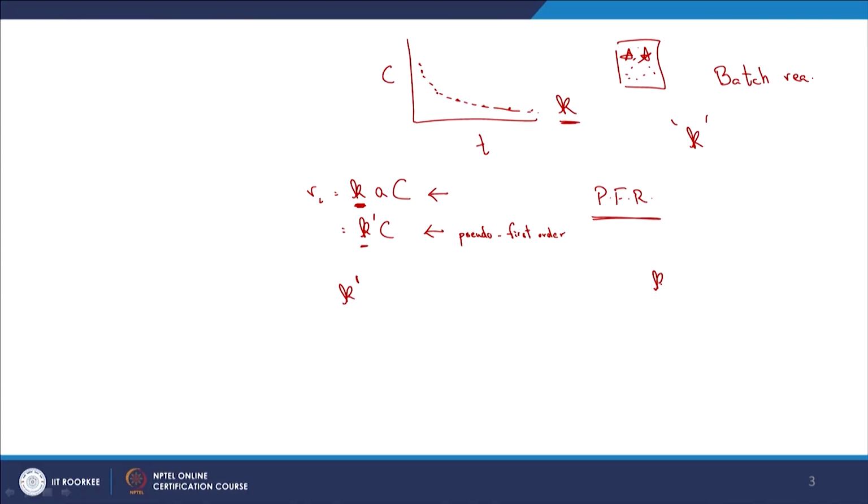As in we know that K dash is equal to rate constant times A, and you know that it is equal to specific surface area times the concentration of the zero valent iron. So, if you do not use the same kind of zero valent iron or the reactive media in your batch experiment in the lab and in the actual case that you are trying to estimate here, then obviously there will be issues. So, you need to keep that in mind.